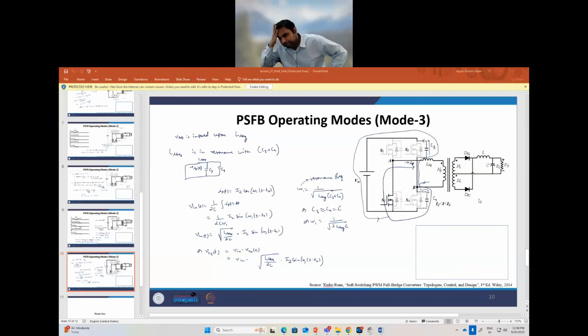The L value you will only obtain using the ripple current. I took 10% or 20%. If you put 20%, it is too large. You put either 5 or 10, your inductor value will go up, but there is no other way you can do it. Okay, I will change that and see it in simulation once. Okay, sir. Thanks, sir.